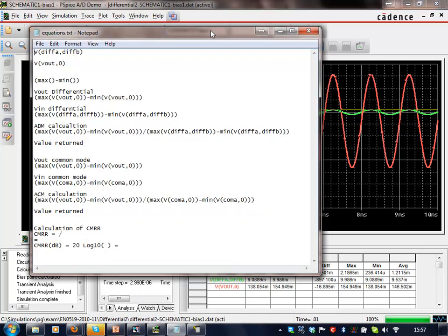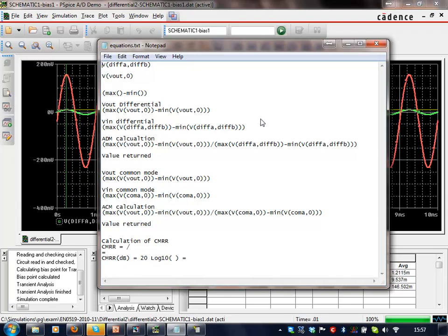Well, you remember me saying that I'd optimized and labeled all my circuits. I've written out the differential signal at the input, the differential signal at the output, and I'd also written out some min and max values. So I can calculate here, using this equation, the maximum voltage out minus the minimum voltage out. If I subtract the two, I get the peak to peak voltage at the output, which is what I want. And I can do the same thing for the input.